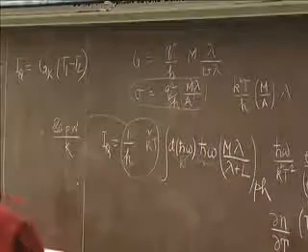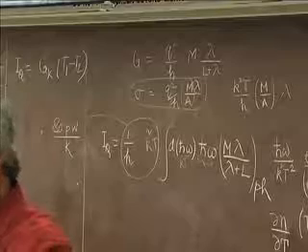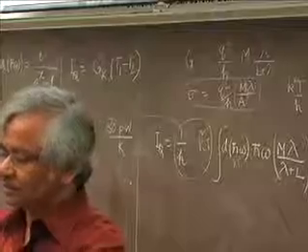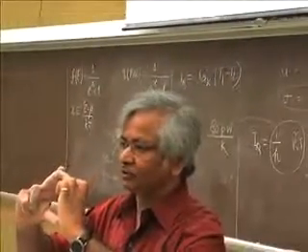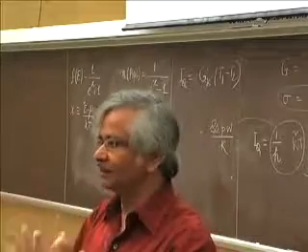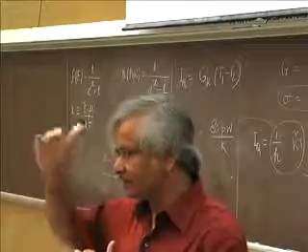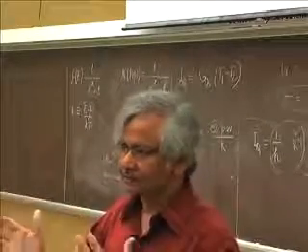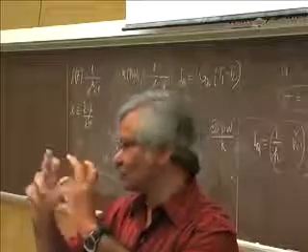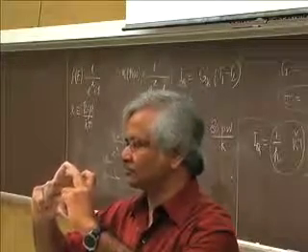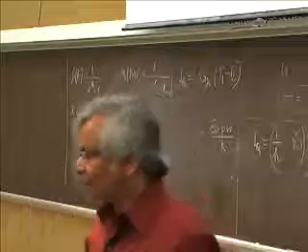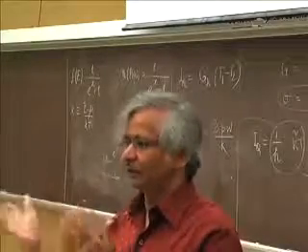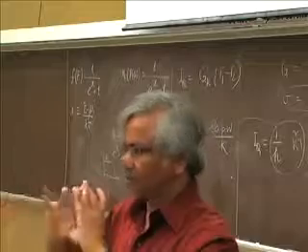With electrons, the way you can think about it, which is not immediately obvious when I define modes as D times v, but with some discussion you can see it, is how many wavelengths fit into a cross section. The big difference between metals and semiconductors is that in metals, the Fermi energy is such that the wavelength is almost the atomic distance. So it's almost like asking how many atoms do you have in a cross section. Whereas in semiconductors, the de Broglie wavelength is more like tens of nanometers, and so the number of modes is a whole lot less.